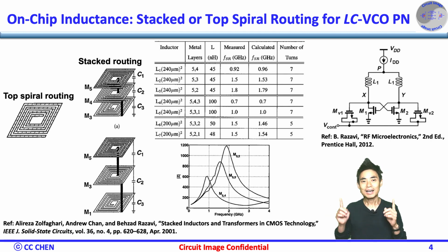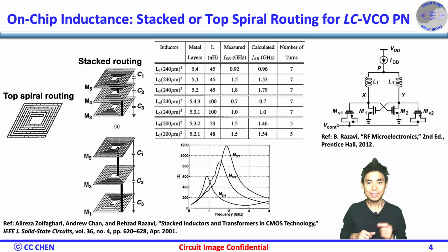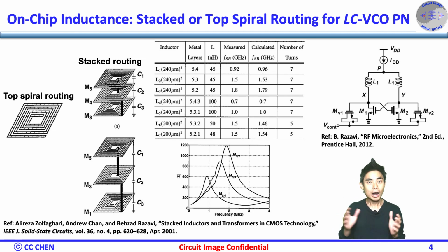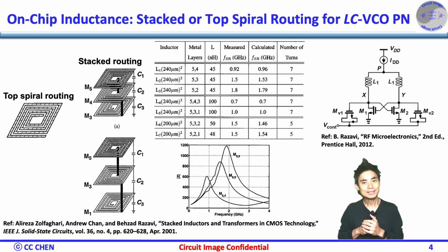Similarly, a high quality factor capacitor in an RLC tank will also improve the PLL's phase noise. A less parasitic capacitance of the inductor will also increase its self-resonance frequency to operate at a higher data rate. Therefore, the RLC image should be clear to you about the area or floor plan impact among different process nodes or even different metal stacks in the same process node.